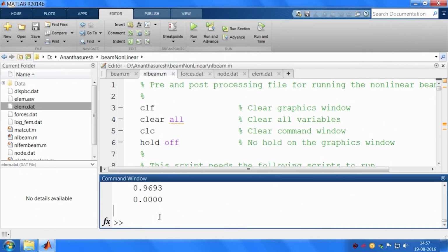So, if I want to look at what is the y displacement, I have to look at degree of freedom 26, u(26). If I do, it will show this is about 10 microns, 9.69 microns for a beam that is 1 meter long that we have taken, and properties and geometry you have, you can go back and check. It moves very little, very stiff, right.